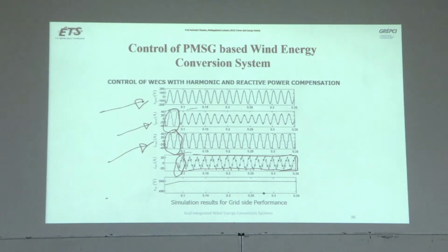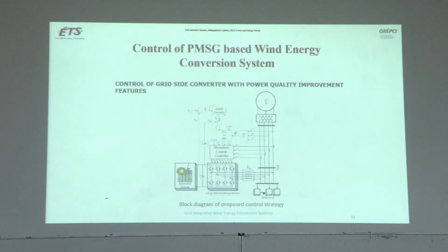So that's why the grid current becomes sinusoidal and less, because power is coming from the inverter; apart from the fundamental component of the current coming from the inverter, you have harmonics also. So the fundamental component will put more grid current. So this is what it is.